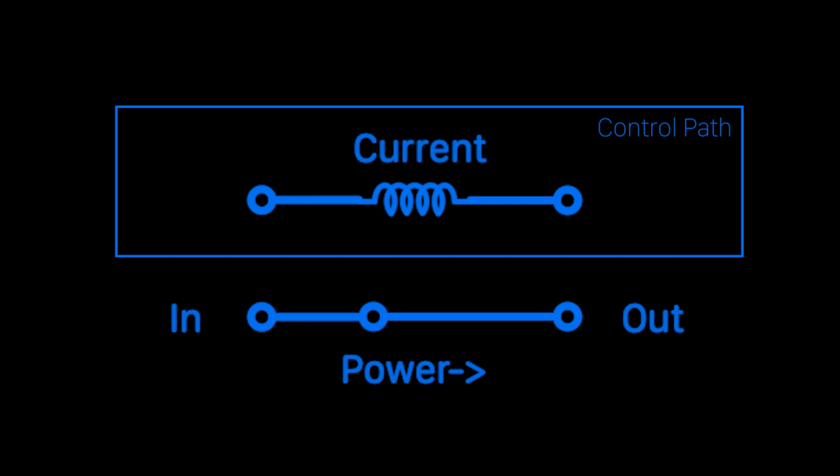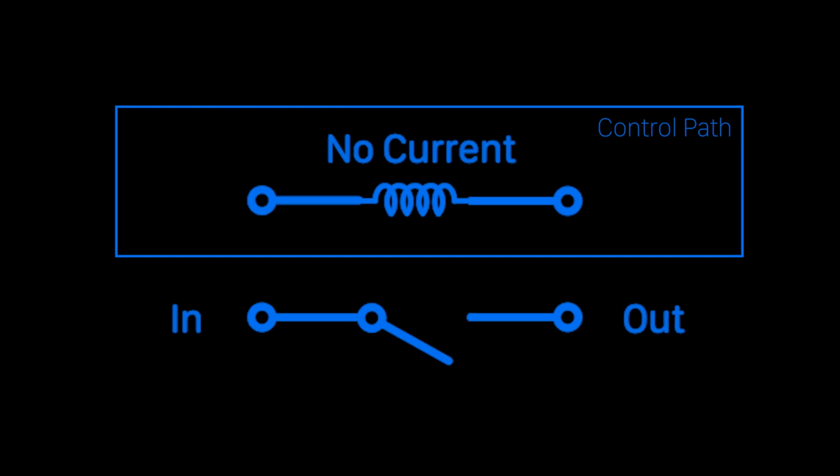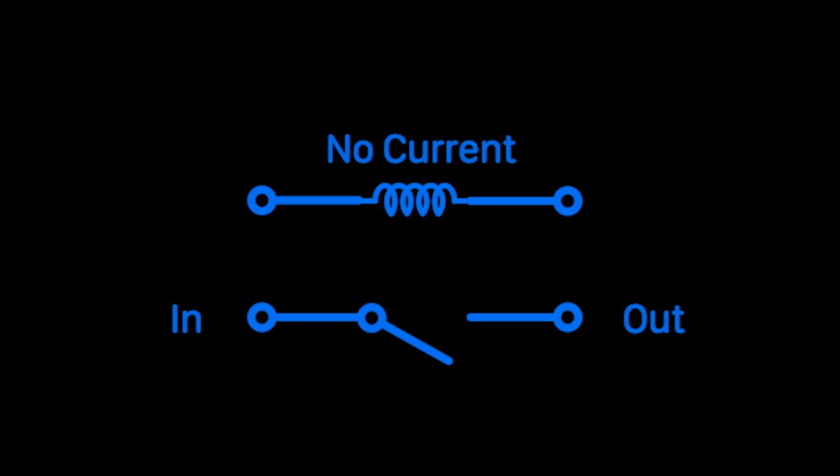Now these other 2 pins are going to control the switch. So if we pass current in one of these pins and out the other, the amount of current is of course going to depend on the relay, but if we do that, then the switch will engage. Once current stops flowing, then the switch will disengage. Maybe it's a plus, maybe it's a minus about relays, is that when they engage, you're going to hear a little click. Now, there are a lot of different variants on this idea. Some relays latch, others have multiple switches and multiple channels, and you also have solid-state relays that don't click.